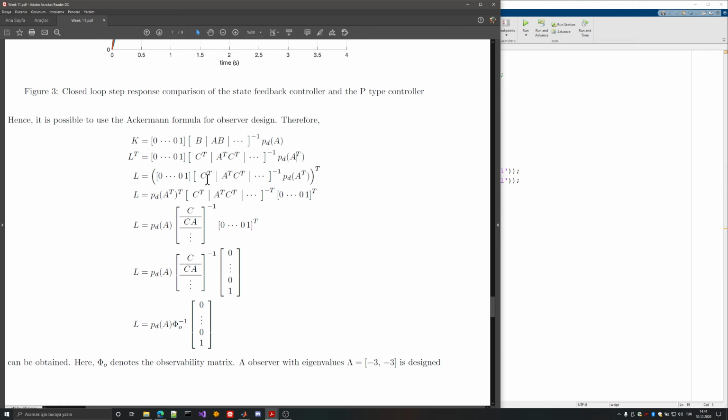You use basically faster poles than for your control system. You look for the settling time of your system, for example, and then determine a reasonably faster observer. It may be 10 times, it may be 20 times faster than the other one. So let's say you have a 10-second mechanical system, then basically a 1 second or faster observer should be enough, because your action takes 20 seconds, so you have plenty of time.